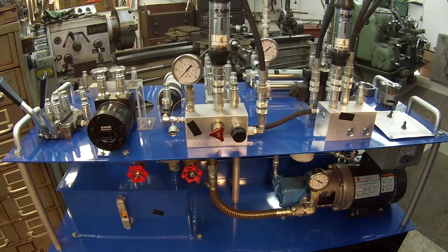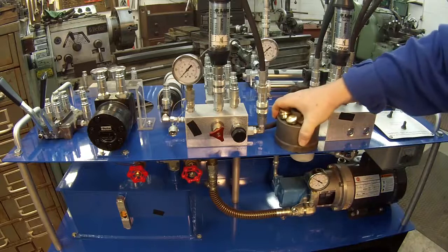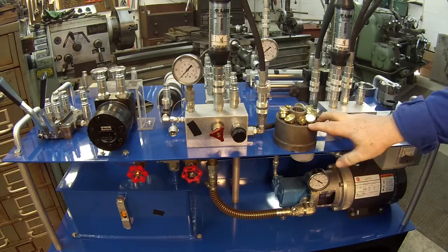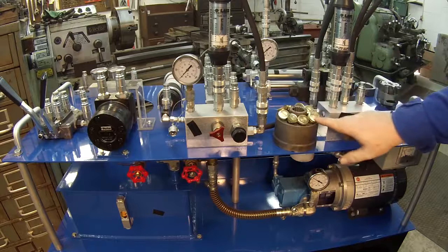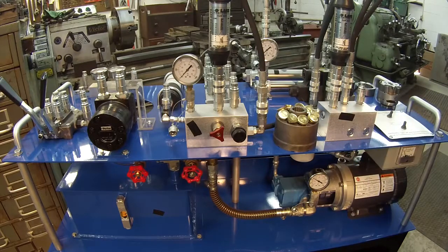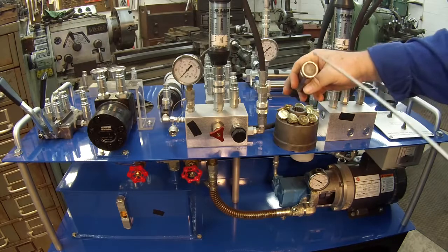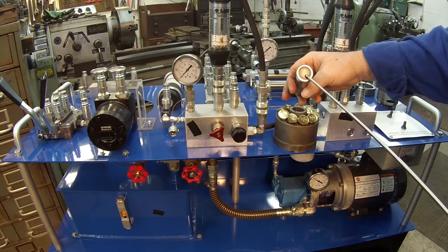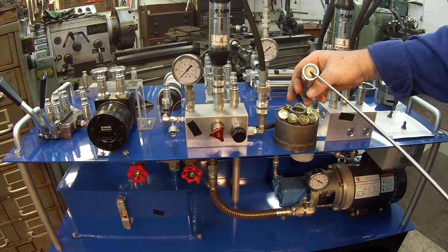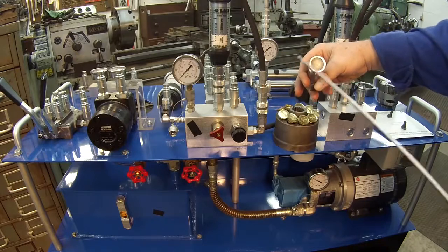Alright, on a piston pump, this is called your rotating group right here on your piston pump, and you see your nice little pretty shoes right there, your little brass shoes that spin around on the inside of your pump. I know it's hard to see, but right there in the middle of this piston is how it gets lubricated. Okay? And here's a larger version of that, so hopefully you can see that. That little tiny hole right there in the middle of this piston is how it lubricates itself as it spins around on what's called a swash plate.